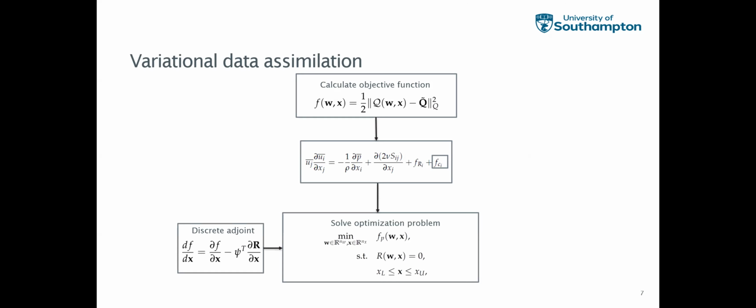And for the discrete adjoint part, to get the sensitivities, we use DAFoam, which is a big benefit, and it's quite ahead in terms of what the others are doing at the moment. And using these sensitivities, we update the design variable, and this process goes on until we get an optimum momentum forcing, which reduces the discrepancy between our experiments and our model output.